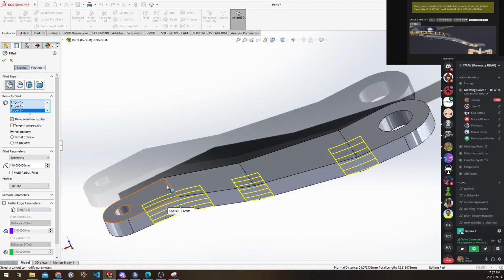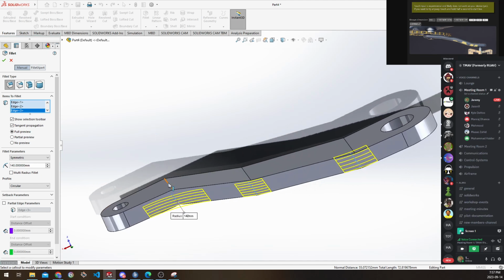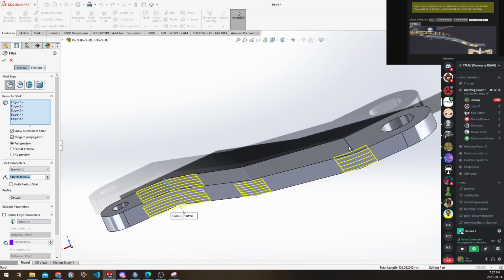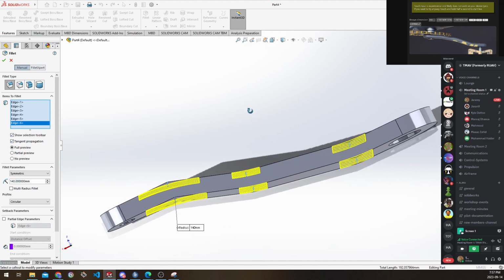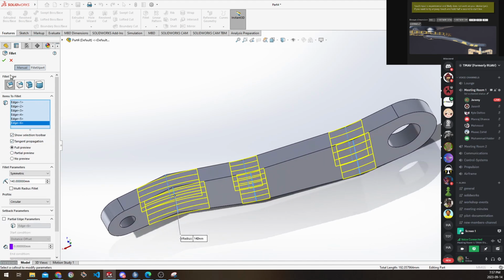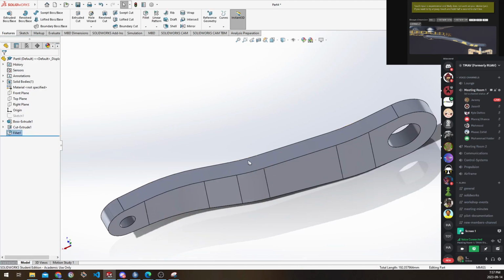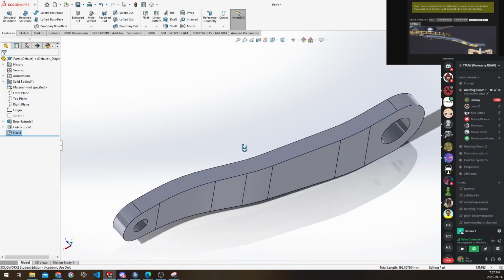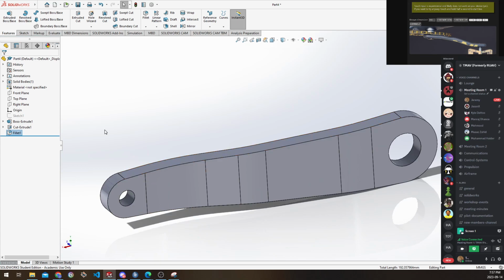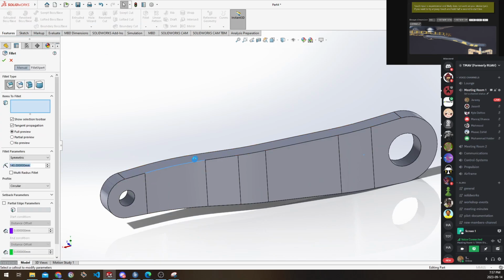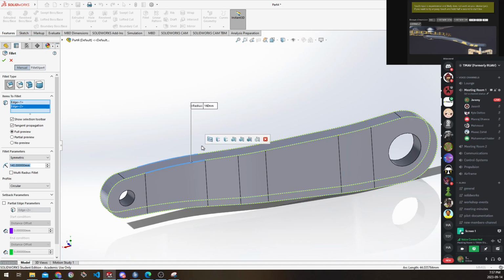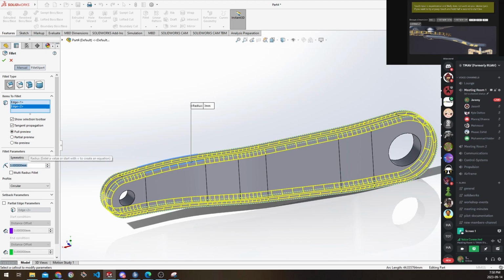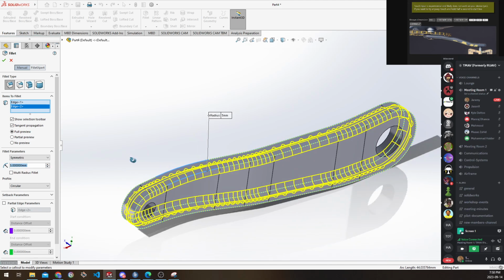So we're going to do this on the major ones. I'm going to pick radius 140 just because it seems to look pretty smooth in the way I want it to. So I'm going to select OK. Okay, so you can see it starts to smooth out quite a lot already. And then what we're going to do is do another one around the edges. Right, and this should select the entire edge around both. I'm just going to work my way up a little bit until I see something I kind of like.